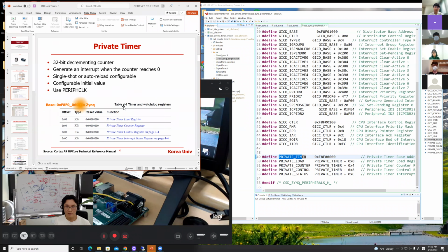Then you do the store operation: F0 to R10. R10 is the LED location. What you want to do is turn on the lower 4 LEDs, then when the counter becomes 0, turn on the upper 4 LEDs.